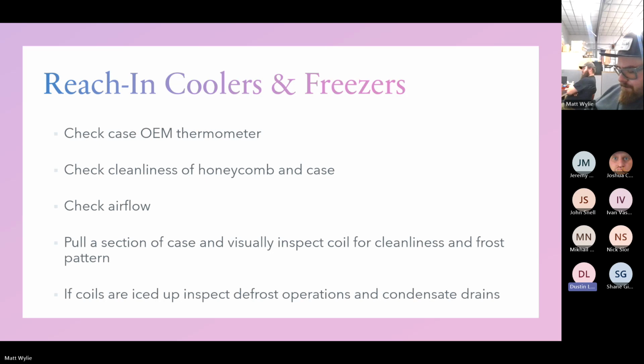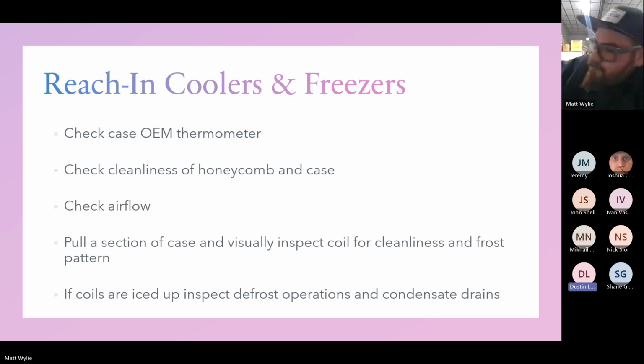And I feel like if it's starving, the frost pattern's a little softer and more flaky, like it's desperate for liquid. That's the type that restricts airflow super quick because it's just building up frost, but the second you pour some water on it, boom, gone. It's like snow. I feel like that usually is your expansion valve starving.